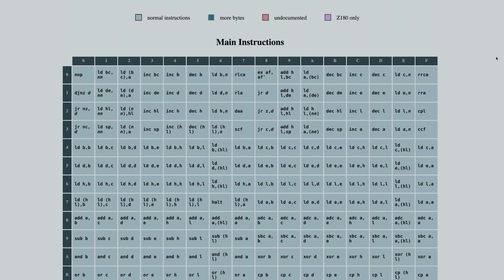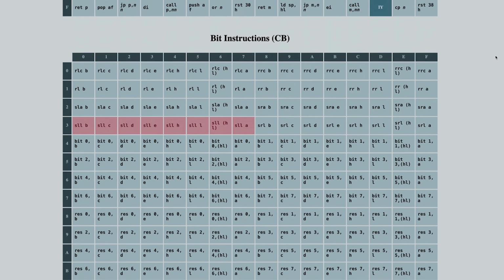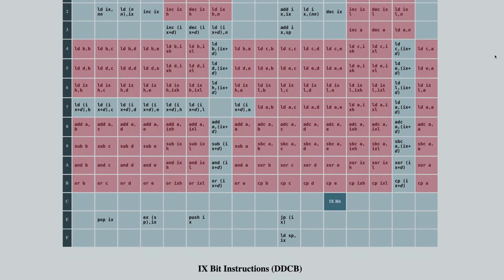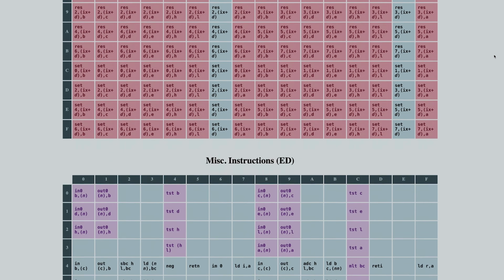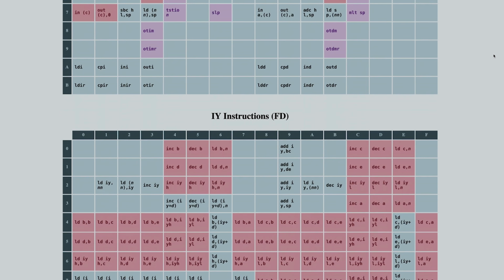The only possible downside is that the instruction has a side effect of storing B in some RAM byte, so you need to worry about where you point IY to. And then it's going to be a little slower than just doing out instructions, but it's really, really ingenious. And the good news is that if other expansions wanted to take that similar approach, there's a lot of room in that table to have hundreds or maybe even thousands of different sequences.